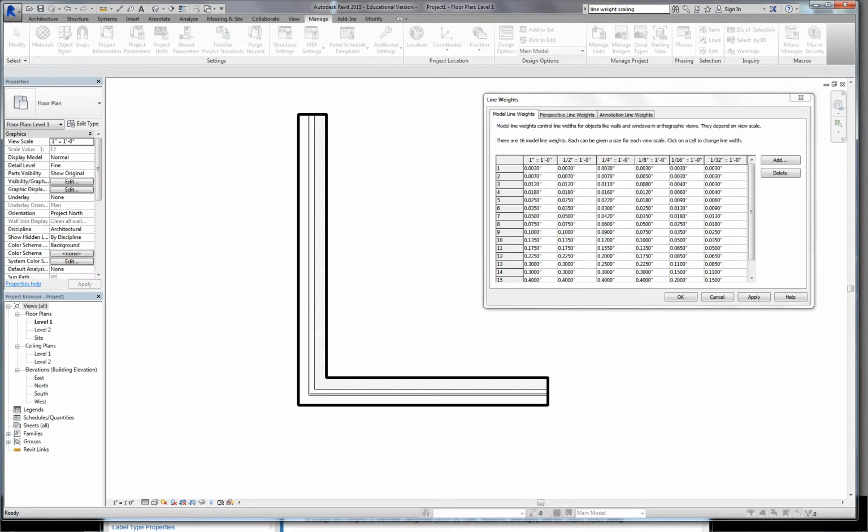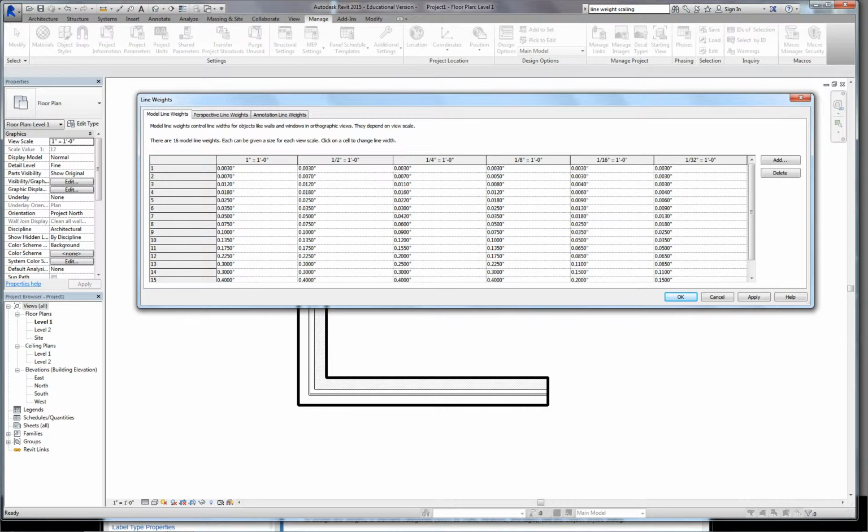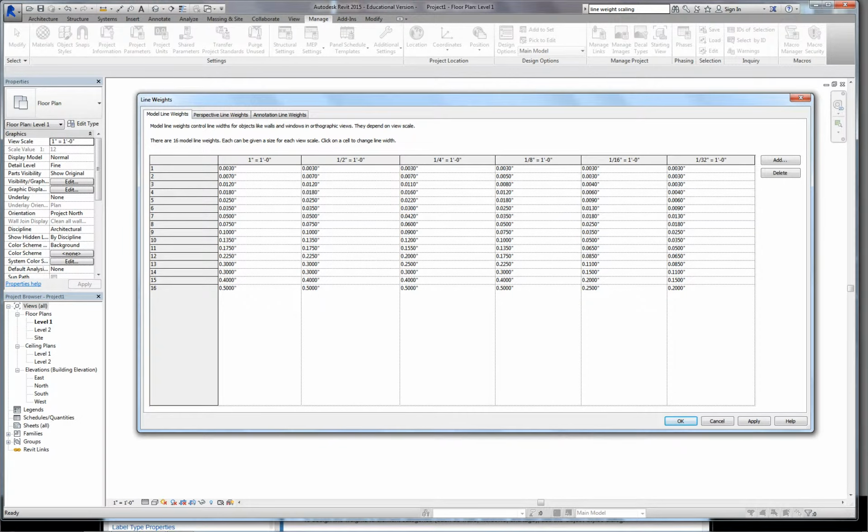So when we're working with line weights in Revit, it's very specific to, in this case, scale. You can see the various scales that we have, and these are the various numbers that are tagged to what these mean. It's interesting that they show them in inches. We're always used to working in millimeters. In AutoCAD, we always see millimeters. In Rhino, we see millimeters, which relates to the pen, like the rapidographs.